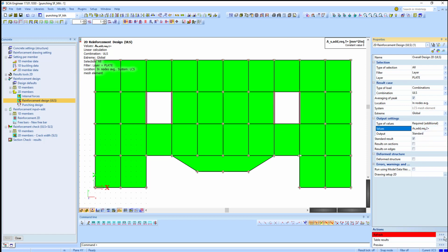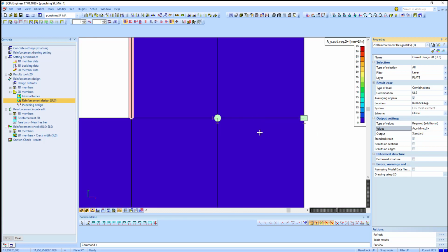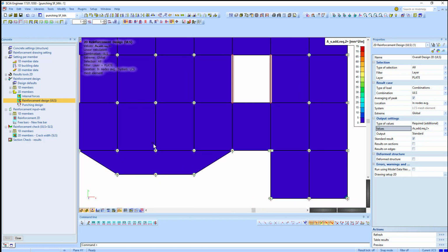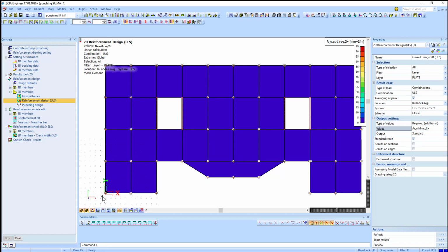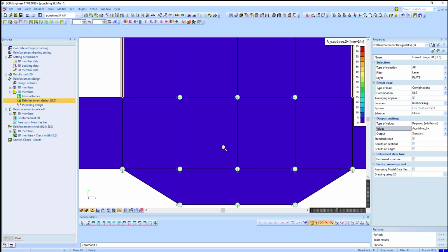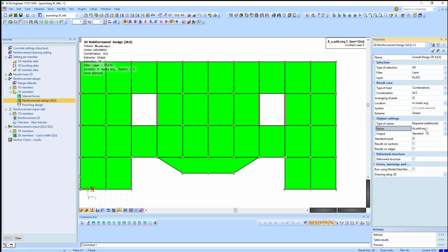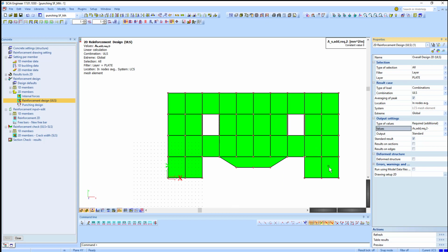If we go in the direction 2 plus, we see a small issue which is coming from extreme stresses somewhere. Here I see some extreme stresses. It's up to me to ignore it or to increase the reinforcement a little bit. The value is 79 square millimeters, so personally I will ignore this value. Next, 1 minus 0 and 2 minus should be 0 also. So my final reinforcement is perfect.